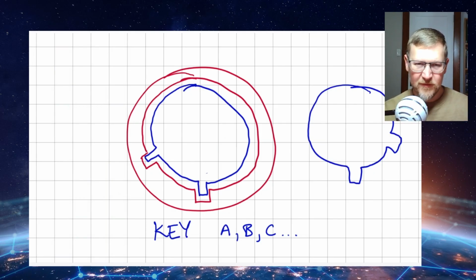So the one side's the plug and one side's the receptacle, and they'll have the same key to match up. And then when you go to the second connector, you might use key B, and the third connector you might use key C. And so that way, even if all three of these connectors are right next to each other, they look almost identical, they're the same size, you can't accidentally put one in the wrong spot because they are keyed differently. And so that's the most common method we use to prevent accidental connections in a setup like that.